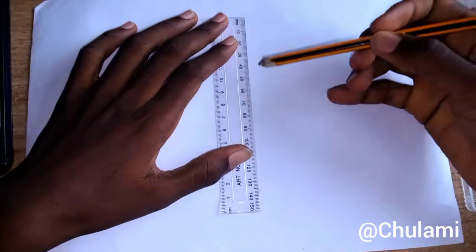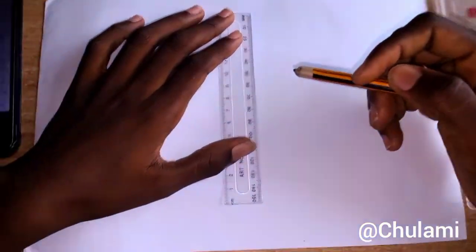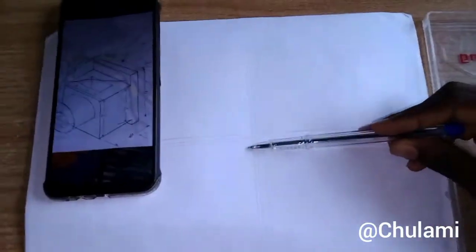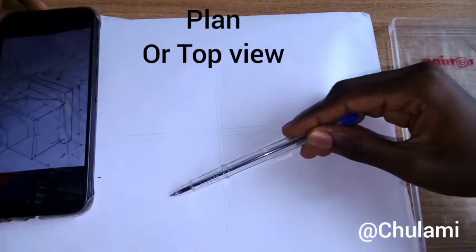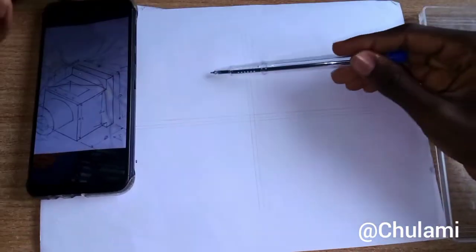First of all, try to draw three horizontal lines and three vertical lines. Okay, now we have gotten this. Remember, we are drawing the views in first angle projection. So we have our front elevation, side elevation, and our plan, or the top view, which is the same thing. So we start from our front elevation.